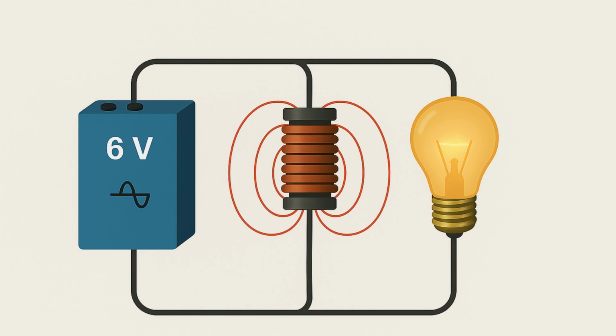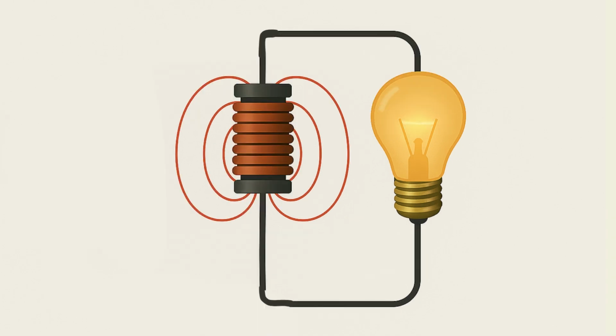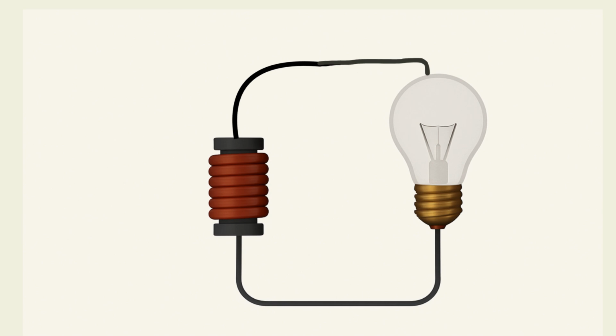When you start a current through an inductor, energy is drawn from the source and it is used to build up the magnetic field. Thus, energy is stored in the magnetic field itself. When the current stops suddenly, the collapsing magnetic field induces a current in the same direction to keep the current flowing. This is how it releases the energy stored.